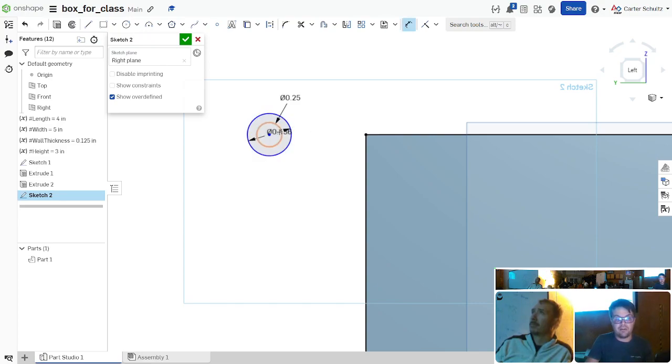and I'm going to put in a tolerance as a gap for how much clearance the hinge should have to be able to move. Just, you know, like 3D printer tolerances, how much free space do I need between the pin and the hinge body? I'm gonna say 50 thousandths of an inch, just so that there's a little gap there for some clearance.